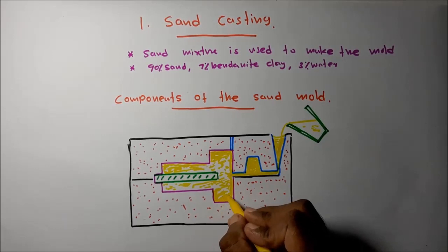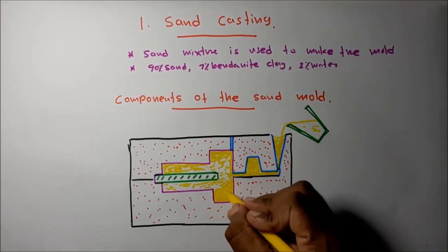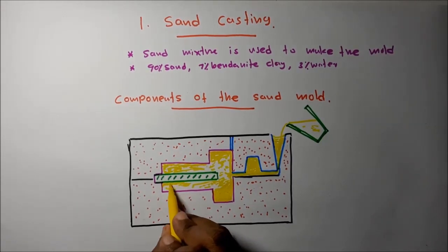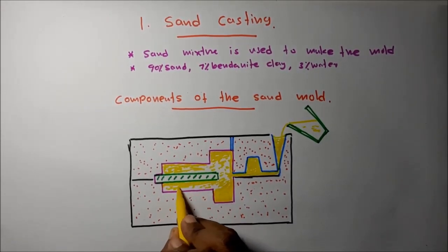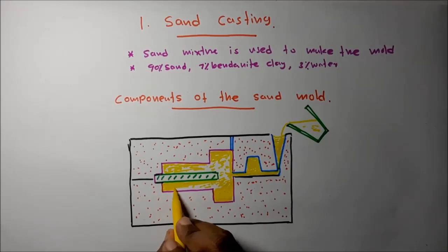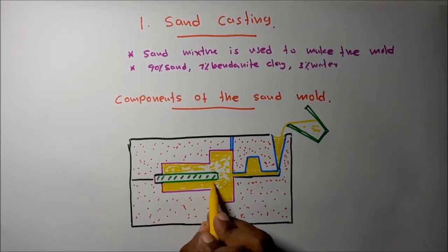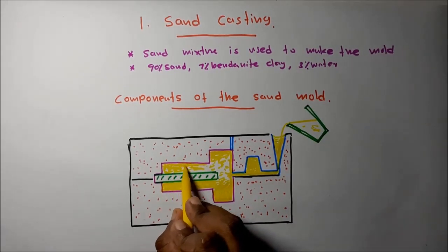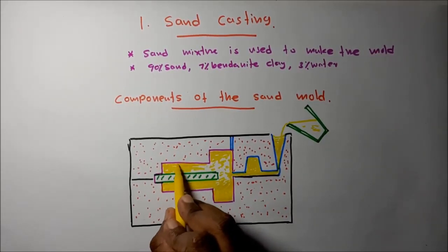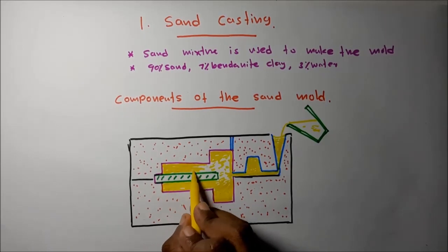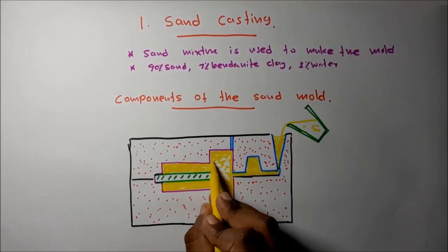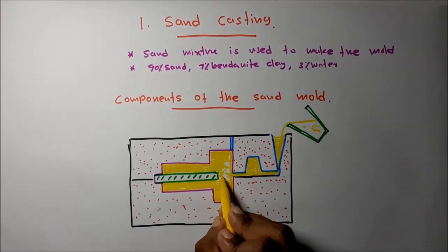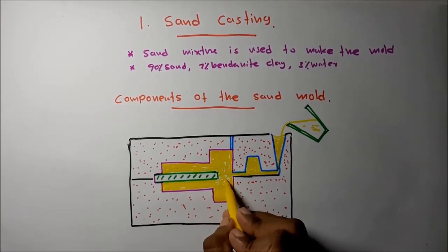A mold does not necessarily have just one cavity. In some cases it has multiple cavities, so in a single casting it can produce multiple products simultaneously. Especially when manufacturing small components, the molds are created with multiple cavities, so at once it can produce multiple items.